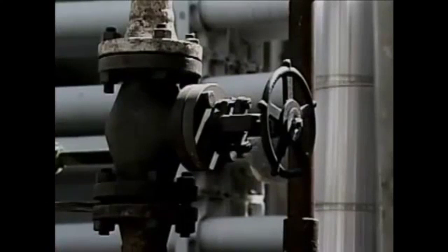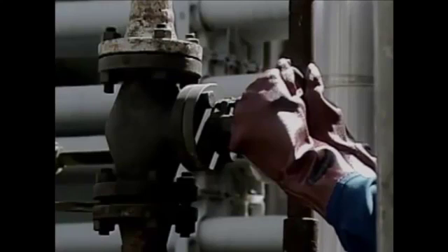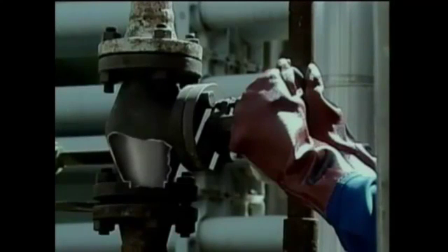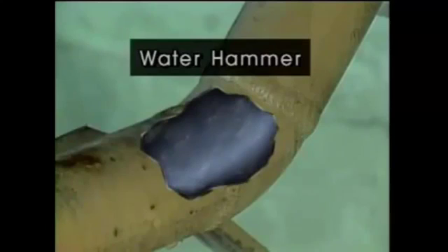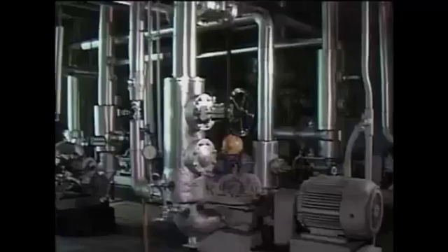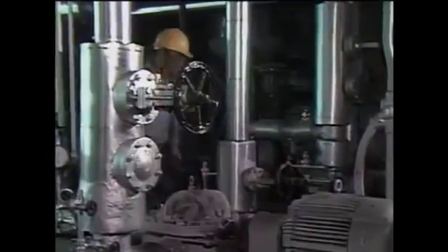For example, it's important that flow control valves in a liquid system be properly adjusted to prevent changing flow through the system too rapidly. The energy conversion from a rapid flow change can create a pressure pulse that travels through the entire system. When the pulse encounters bends or restrictions in the piping, it slams into them, causing a shock to the system known as water hammer. In severe cases, water hammer can cause piping to rupture, or it can damage other system components. By following operating procedures, you'll stand a better chance of avoiding these types of problems.